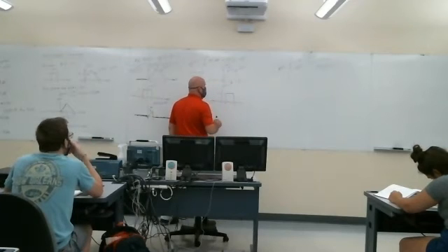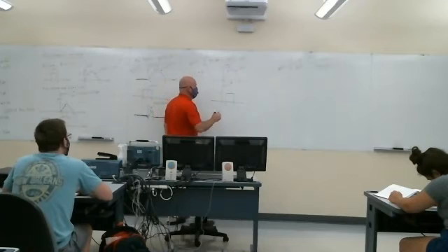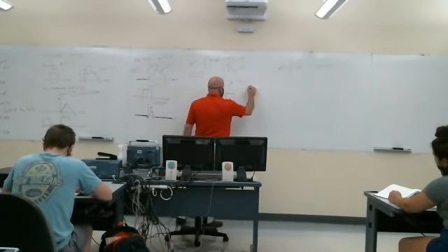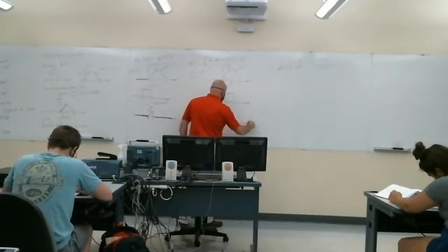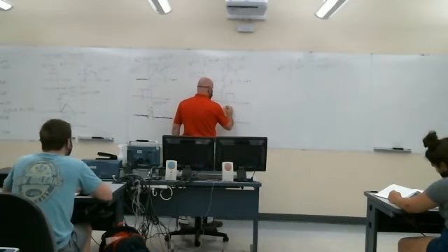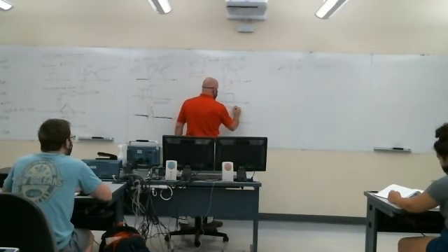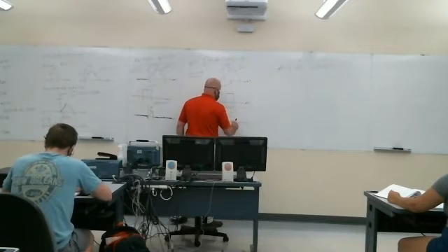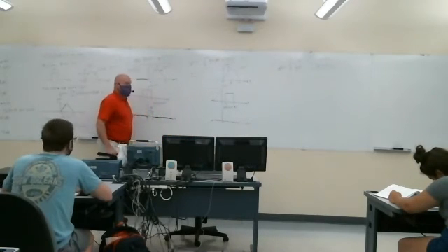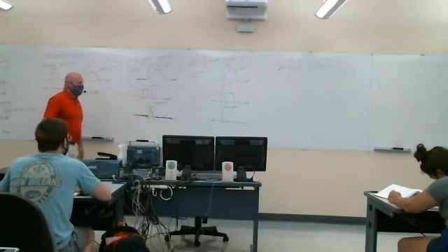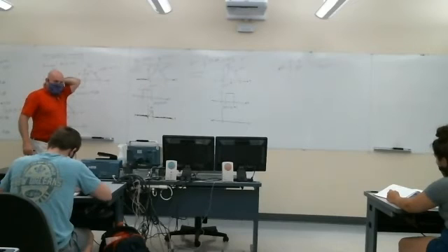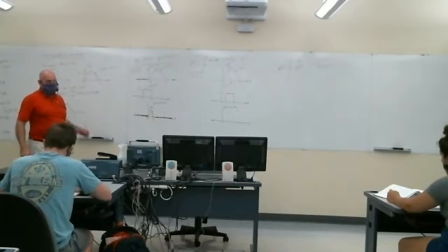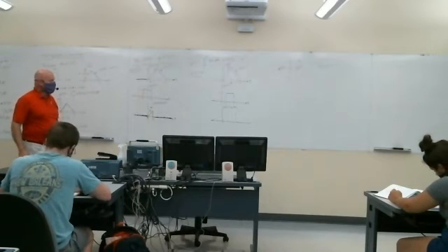This has a height of 2. This is tau. I'm going to give you a minute to sketch. It doesn't have to be exact, but roughly what the shape of h of tau times x of t minus tau is. What I'm particularly interested in is, where is that product non-zero? Because that's going to determine the limits on my integration.